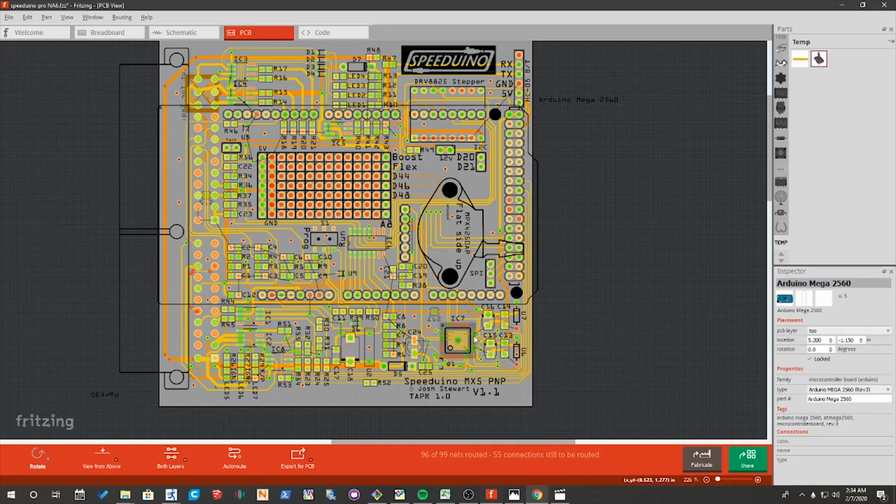So if we grab our voltmeter, we're able to check pin 20 by checking the 5 volt rail of our proto area, and then we can check the 5 volt circle all the way up here to check pin 17 to see if that's outputting 5 volts as well.